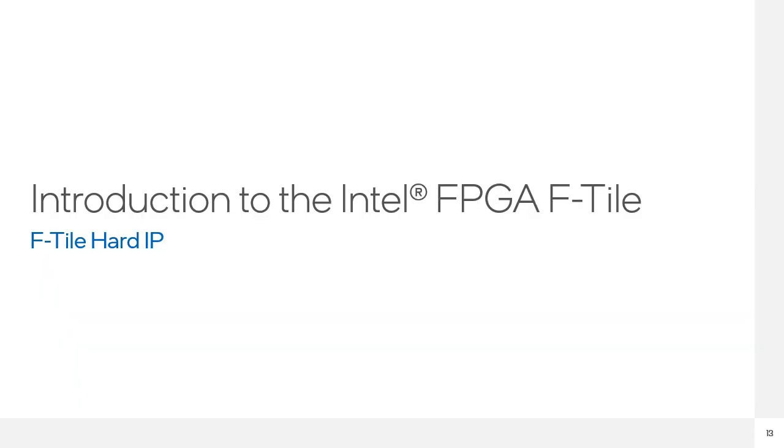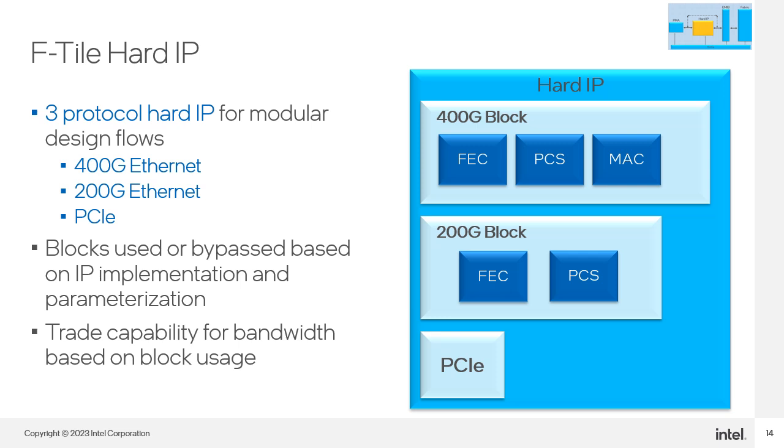Now let's talk about the hard IP. The F-Tile has 3 protocol IP: a 400G Ethernet, a 200G Ethernet, and a PCIe hard IP. This allows users to mix and match interfaces according to their needs. Within each hard IP, hardware blocks can be enabled or disabled according to how the IP are configured in software. This solution allows users to trade features for bandwidth, depending on which hard IP and the blocks within that are chosen.